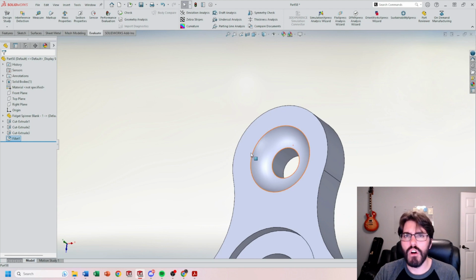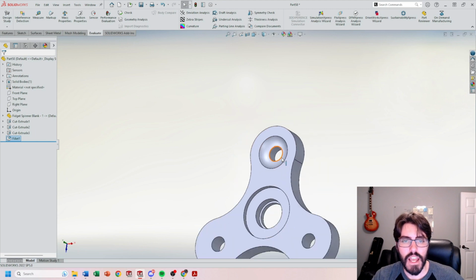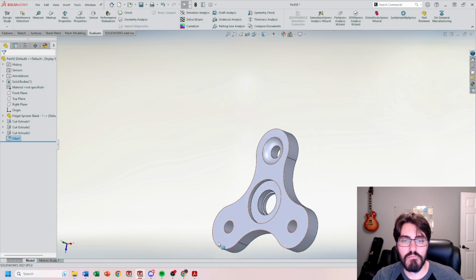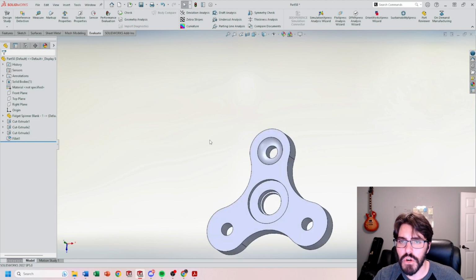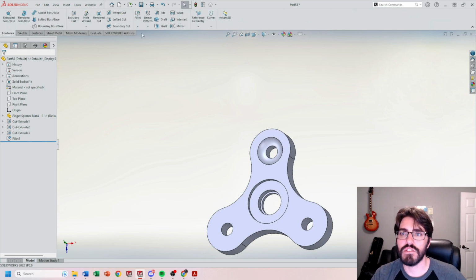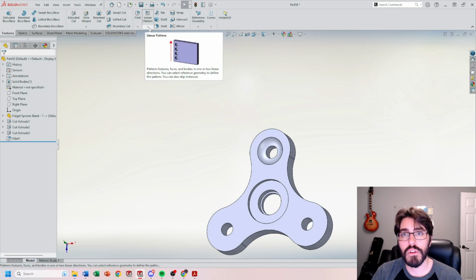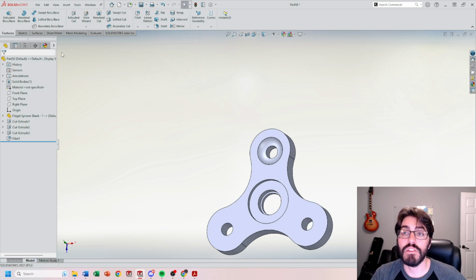Again, you could probably just draw the circle as is, two sides, and then fill it in that way, but I just wanted to show you how you can control a fillet command using that overflow. All right, and we're going to go ahead and pattern this around and then mirror it to the other side. Much like what we were doing in the sketch command when we were doing sketch patterns for circular, we're going to use the Features tab and the circular pattern there.